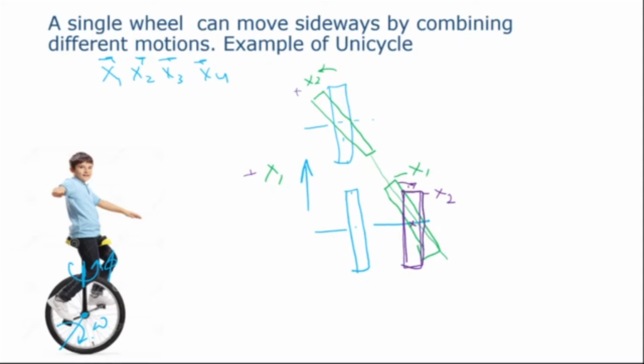That means this point here in the configuration space is accessible. The robot cannot go sideways, or this wheel cannot go sideways, but by using different maneuvers, it can actually go to a position there. That means the system is fully controllable because it can go and position at every point in the workspace.